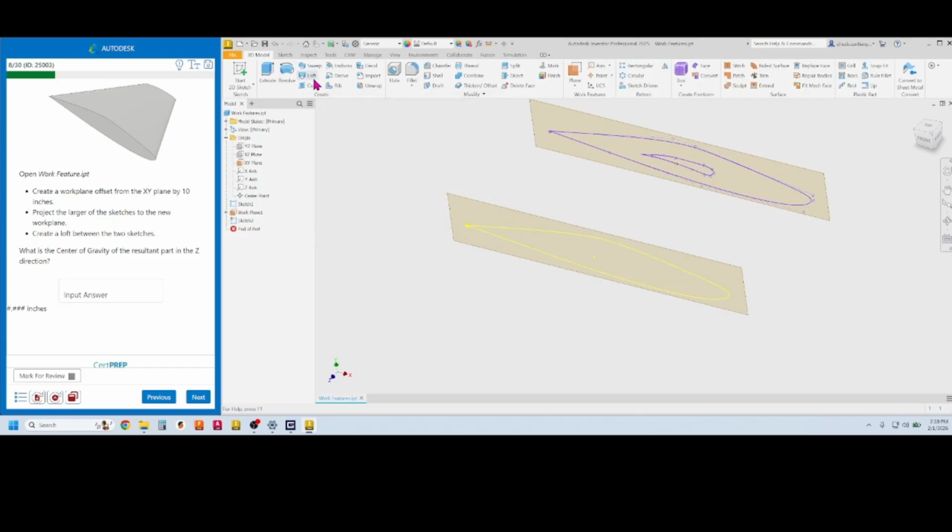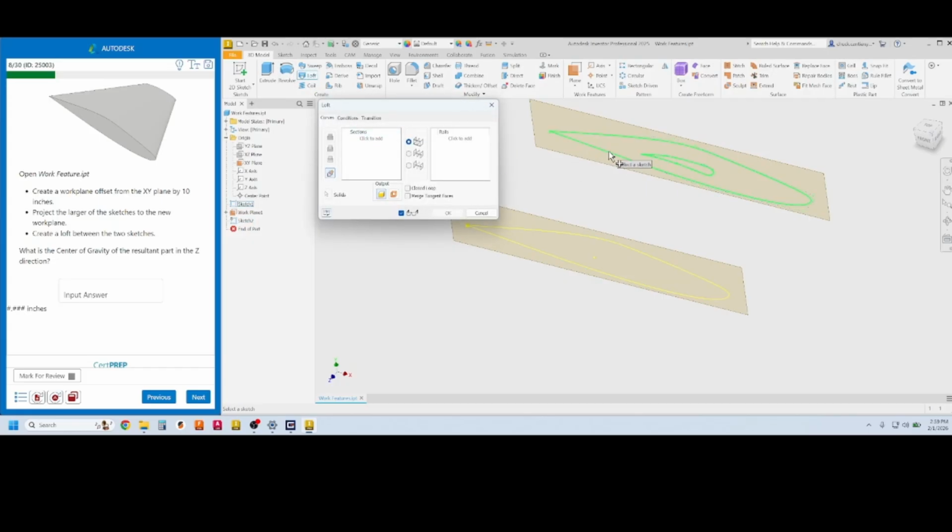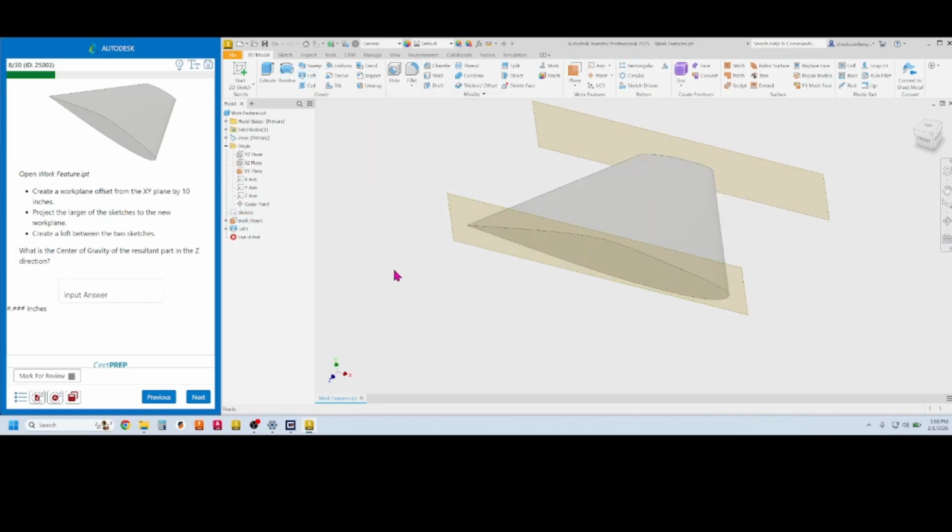here and check that. So I'm going to go back to loft. I'm going to which loop to use. So I have to pick a loop. So I want to make sure I get just that inner loop highlighted. Inner loop. And then when I come out, yeah, now when I come out here, I can't click it. I have to click to add. Now, view of my loft, I say, okay. That gives me my loft.